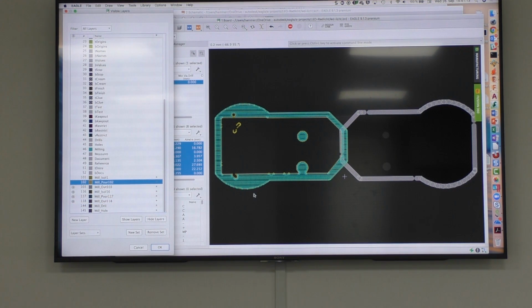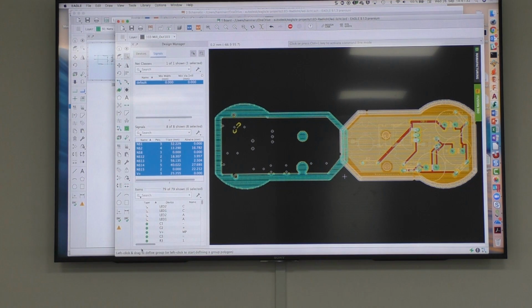Basically the same. So I made a script now, but if I use CNC, for example, then you can create CNC data, you can feed a milling machine, and you can mill out the board outline. So it's quite often used. It works pretty well. Something that people use if they have a small milling tool at home. You could send it to the big one. But I think I have no access to that. What else?